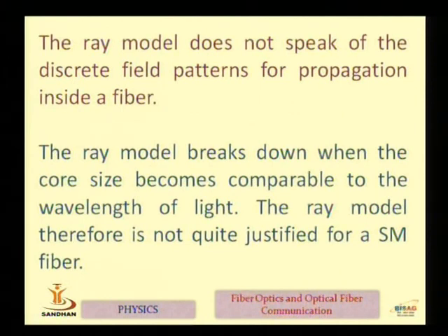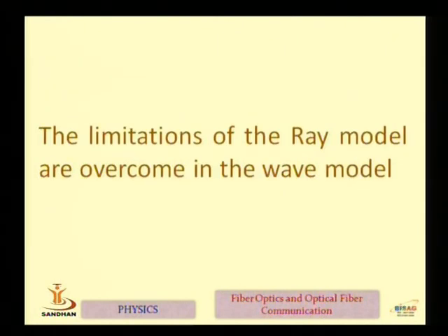The ray model does not speak of the discrete field patterns for propagation inside a fiber. The ray model breaks down when the core size becomes comparable to the wavelength of the light. The ray model therefore is not quite justified for a single mode optical fiber. The limitations of the ray model are overcome in the wave model.